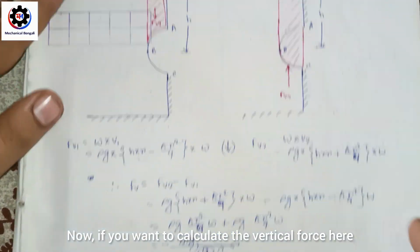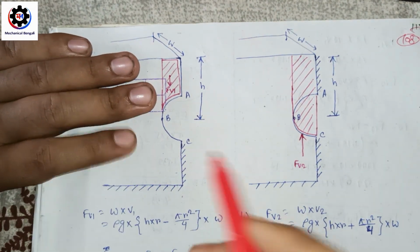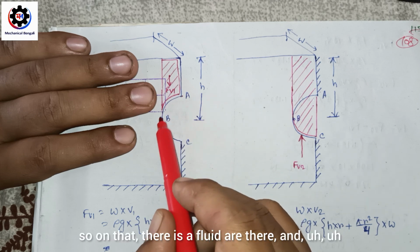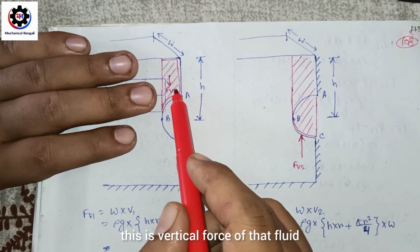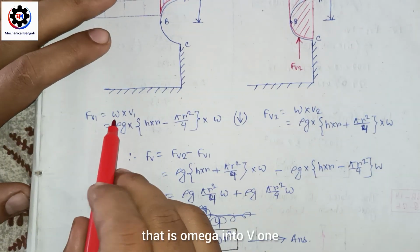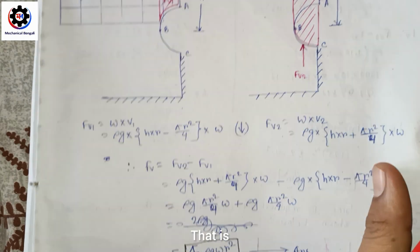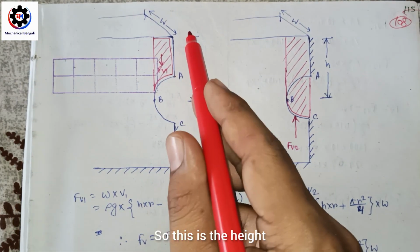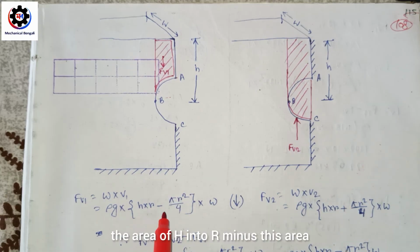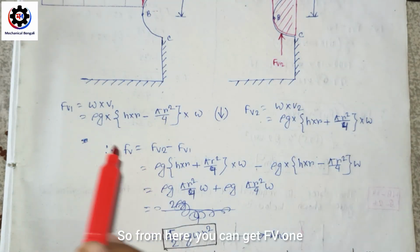Now if you want to calculate the vertical force here, there is a fluid on the left side. So this is ABC, the semicircular gate. On that there is a fluid, and this is the vertical force of that fluid, that is FV1. If you want to calculate FV1, that is omega into V1. Omega is equal to rho into g, we know that. And what is the volume V1? This is the height. So what is the area of this? Here to here the area is h into r minus this area pi r square by 4, into w, the width of the plate. So from here you can get FV1.